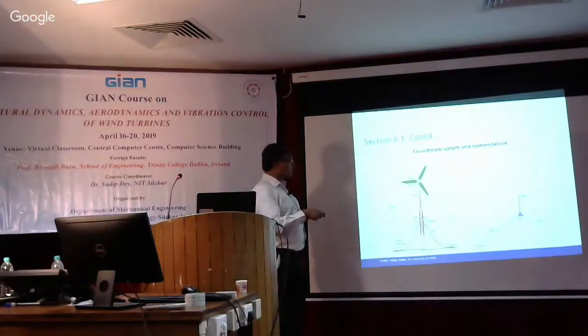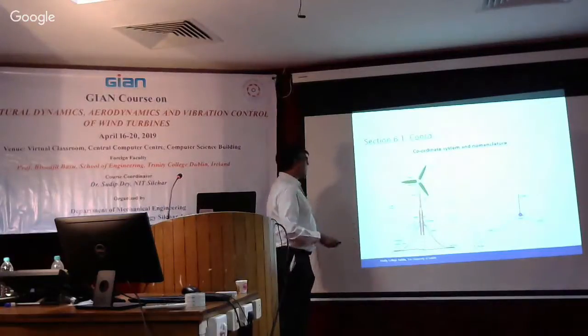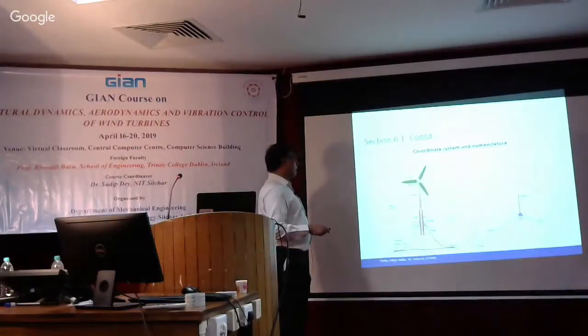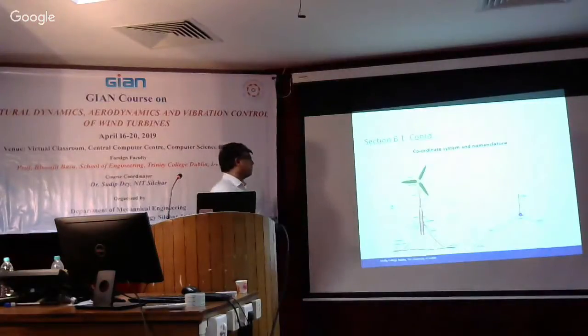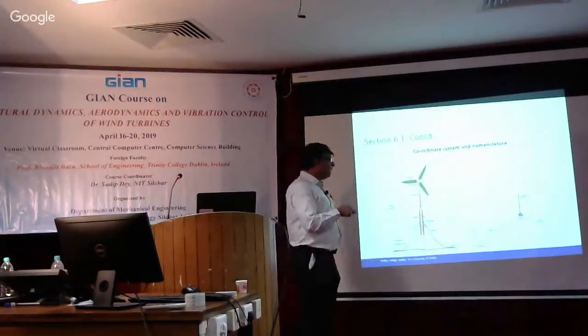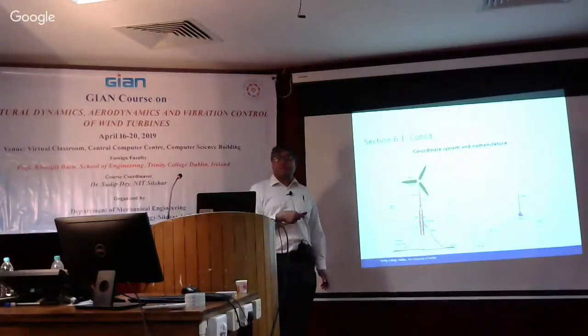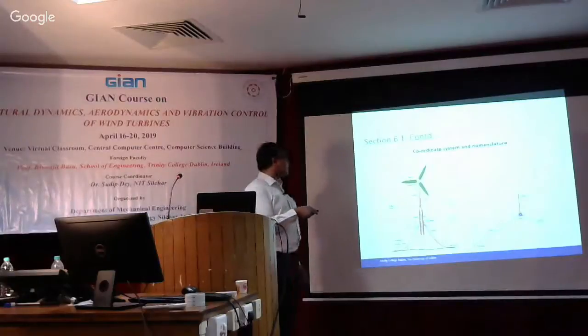So heave is the vertical motion. Sway is this motion. Surge is the out of plane motion in this case. Then you have 3 rotations, which are the yaw, which is about the vertical axis, the roll, and obviously the pitch. So pitch, roll, and yaw are the 3 rotational degrees of freedom, and sway, surge, and heave are the 3 translation degrees of freedom. So 6 degrees of freedom.